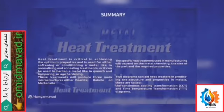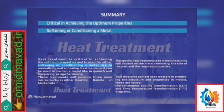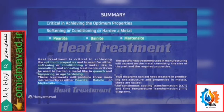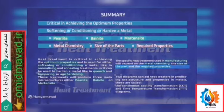So to summarize, heat treatment is critical in achieving the optimum properties and is used for either softening or conditioning a metal, like in normalizing and annealing treatments, or it can be used to harden a metal, like in quench and tempering, or age hardening. These treatments will produce three main microstructures, either pearlite, bainite, or martensite. The specific heat treatment used in manufacturing will depend on the metal chemistry, the size of the part, and the required properties.